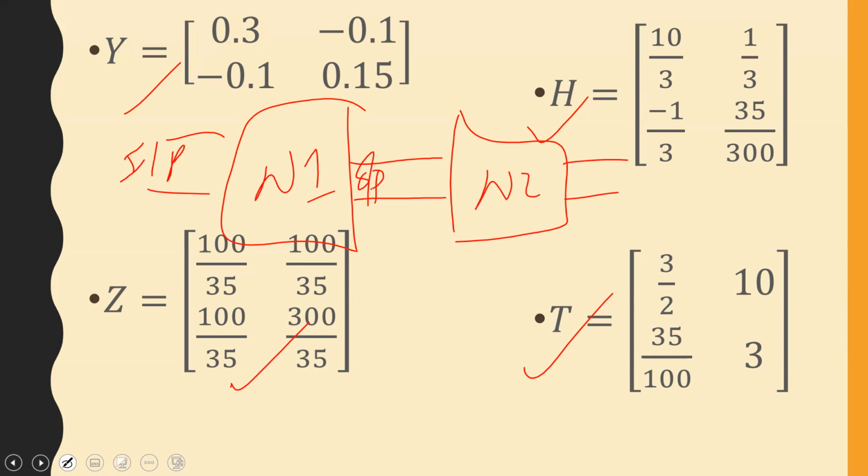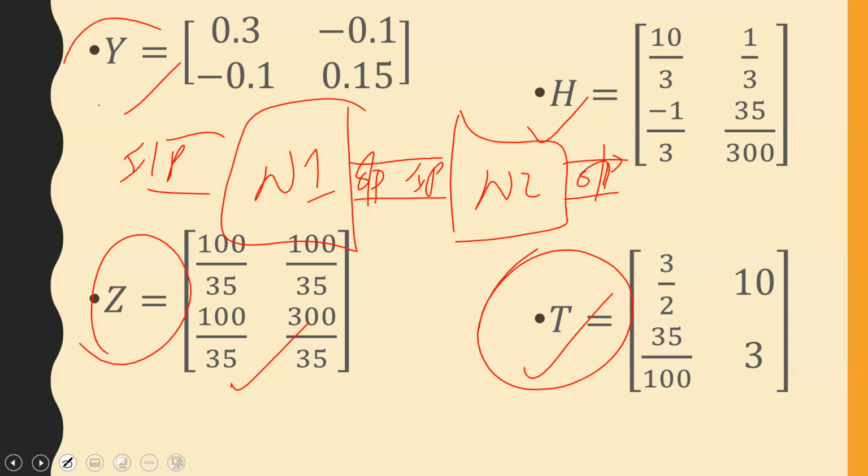This is the output of network 1, this is the input of network 2, and this is the output. If we have this setup, it is best if we had the transmission parameters of both networks. If I had the networks connected in series, for example, it may be best that I have the impedance. Then again, if they are in parallel, it may be best if I have the admittance. Good? So we will need to move from one set of parameters to the next.